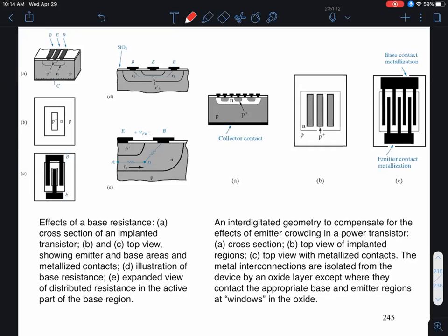All right, so if that's the case, where would I get a higher emitter current density? Well, clearly it'll be at the surface region, because that's where the effective base emitter forward bias is the highest. This effect is known as emitter current crowding effect. And it's not a good effect because that causes local heating in the surface region of the transistor. And there are second order effects that I haven't gone into. You basically get high level injection effects as we discussed for diodes, and the overall BJT gain would suffer.